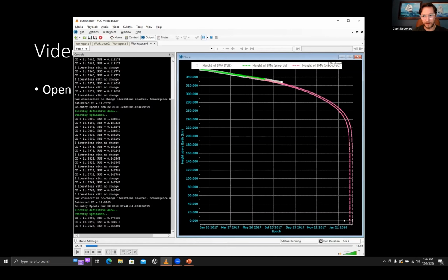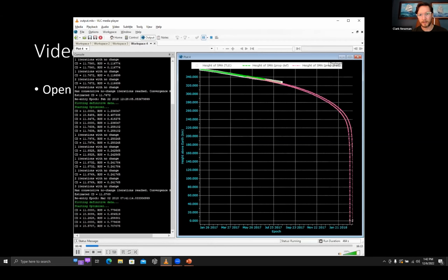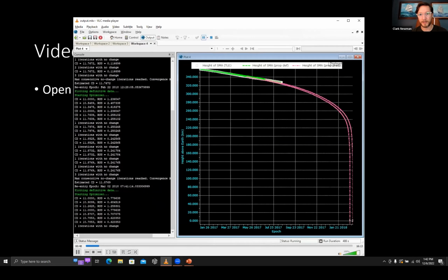And so you can see that our estimate has actually shifted forward in time as we input 100 new TLEs. To be clear, we are kicking out the first 100 TLEs, adding 100 newer TLEs, and repeating the process. And so that's happening again. We shifted the window forward again. And this time you can see that the altitudes observed by the two-line elements start to slip above where our previous propagations have estimated it to be.